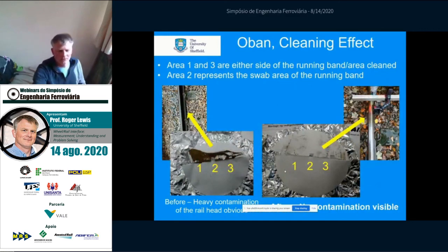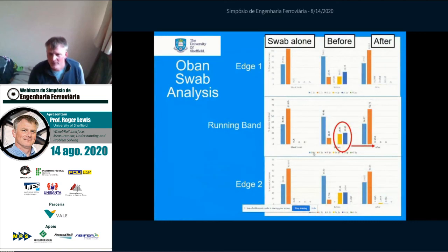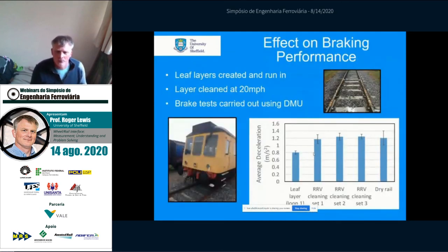So here, the left-hand swab, heavily coated in oxide. Here, less material. The only material on the swab actually came from the edges of the clean track. So in the middle, number 2, we're not cleaning anything off. We analysed that. That essentially showed that on the swab after cleaning, the only materials present in our analysis were the swab materials. So, very successful trial.